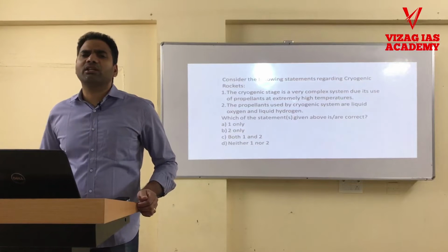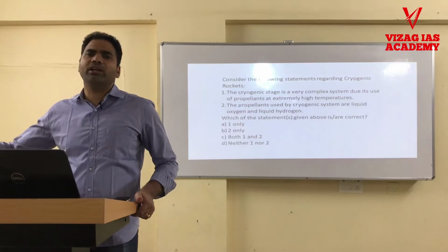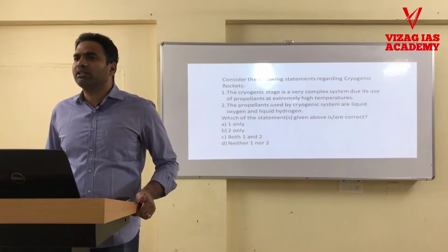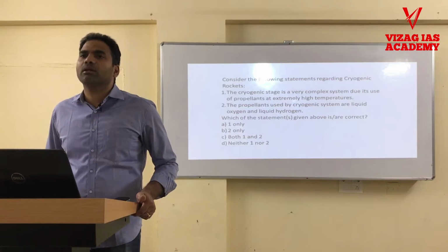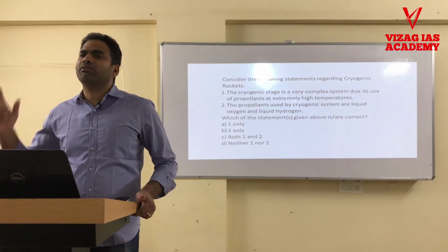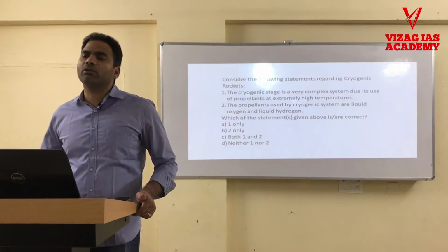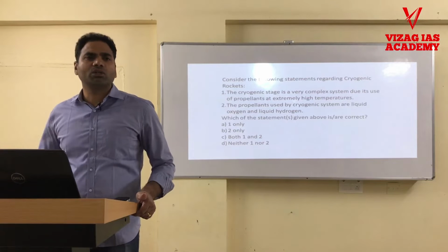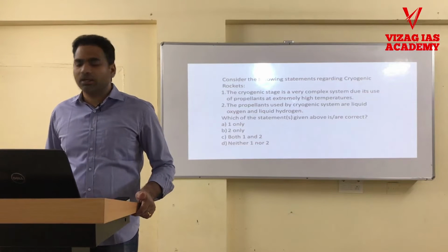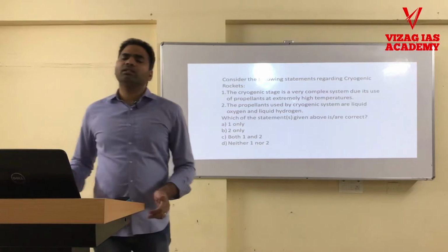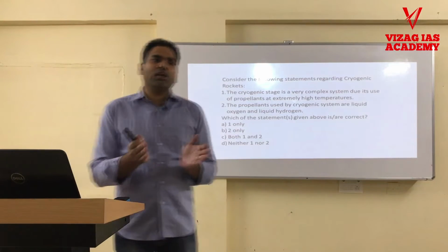Why shouldn't we use other fuels? We already use solid and liquid fuels, right? For a gram of cryo fuel consumed, you get more thrust when compared to other solid or liquid propellants. That is the main advantage, because of the highly calorific value.